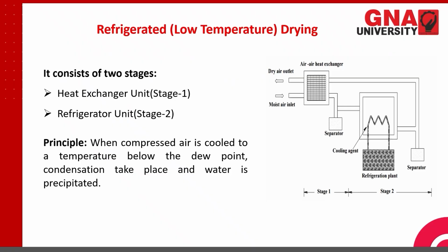Now you see, the next point is refrigeration cooling, that is the chiller section, stage 2. The pre-cooled air then enters the air to refrigerant heat exchanger, that is the evaporator. So same as in our refrigerators. Our refrigeration cycle cools the compressed air further to 2 to 5 degrees, that is the dew point temperature. At this low temperature, the water vapor in the air condenses into liquid water.